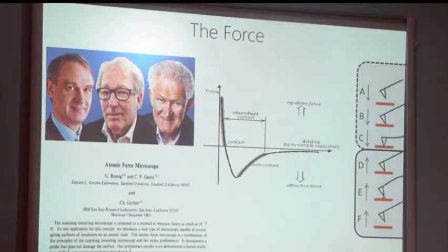And this is not a single force, it's a mixture of forces which includes van der Waals forces, magnetic forces, electrostatic forces. So let's say all these attractive forces act when the probe comes very close to the substrate within the range of 2 to 10 nanometer. But then tip can also touch the substrates, and when the tip touches the substrates, the only force that exists is electronic in nature. So electrical repulsive force starts to work. So until this point, when you have no contact between the tip and the substrate, this is called the non-contact regime. And when the tip is completely in contact with the substrates, you have the contact regime.